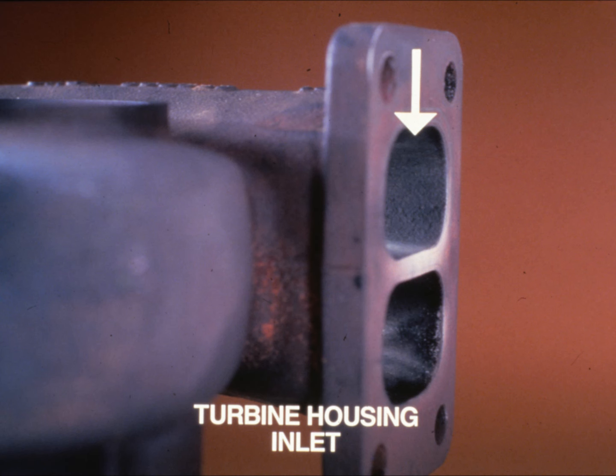A light coat of carbon is normal. Cracking or missing pieces indicate excessive exhaust temperatures. If the inlet is wet with oil or has excessive carbon deposits, an engine problem is likely. Record defects on your checklist.